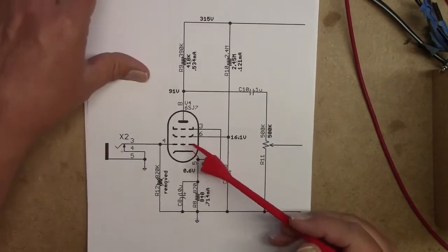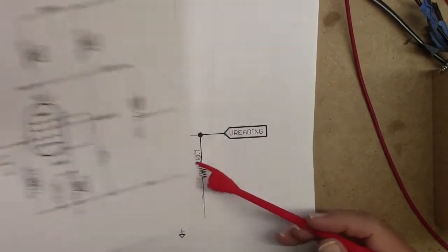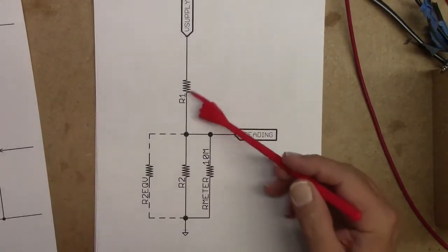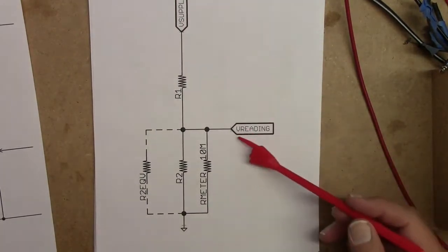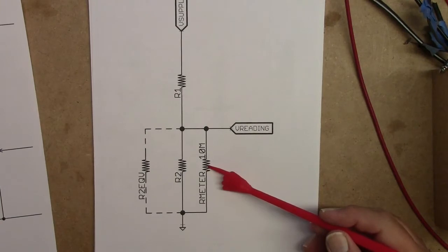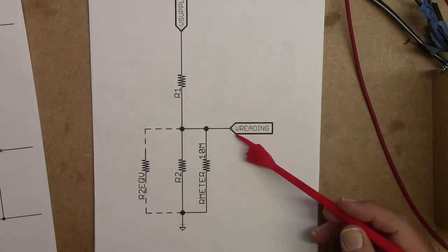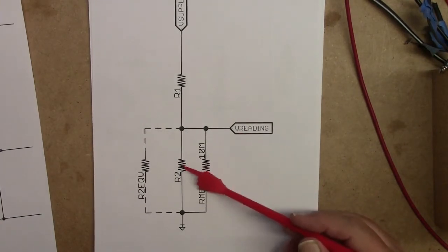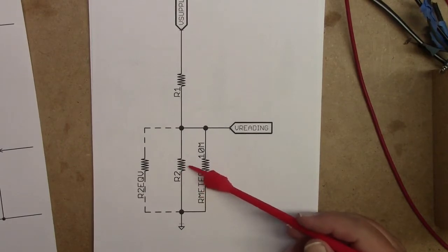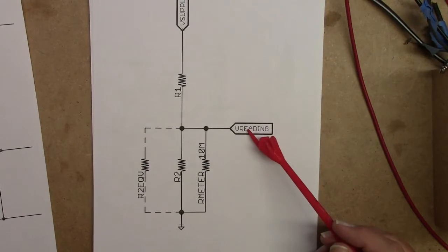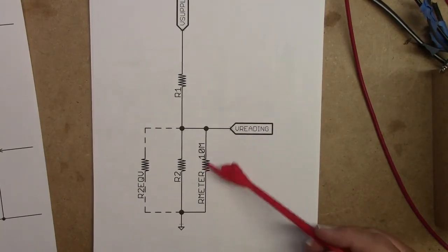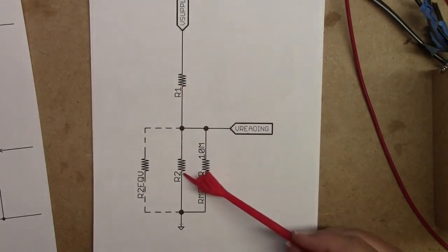So it really kind of looks like this here, where you have the power supply up here. Here is your meter input impedance, and this is the reading on the meter. And then you have this unknown resistor here. And if you know this voltage and you measure this one, you know what this is, and you also know what this is, you can determine what R2 is.